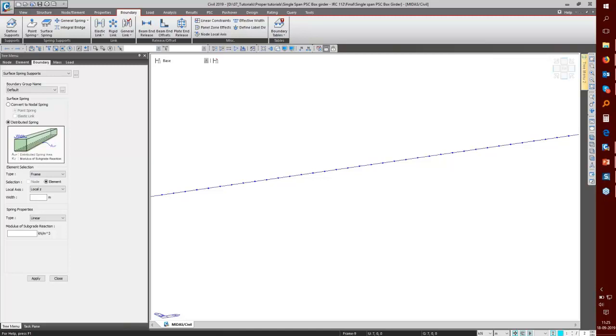again, as I said, this is not the exact analysis. We are doing an approximate analysis to simulate the soil behavior. When we have two layers of soil, we get non-linear behavior, that is, based on the deformation, what the stiffness of the soil would be. When we know it is a two-layer soil, we can model the two-layer behavior in geotechnical software. In the case of Midas, we have Midas GTS NX. We can model that, apply the loads occurring here, and extract the multilinear soil springs.